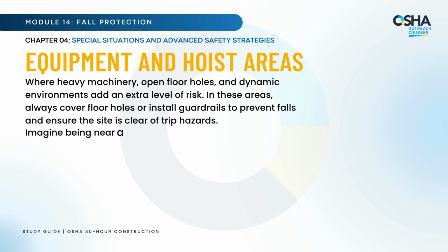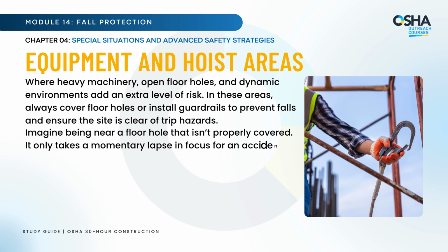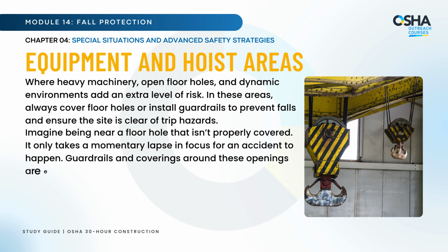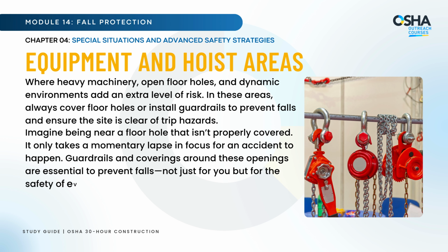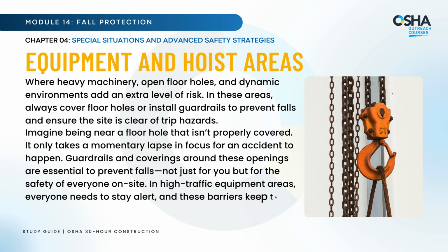Imagine being near a floor hole that isn't properly covered. It only takes a momentary lapse in focus for an accident to happen. Guardrails and coverings around these openings are essential to prevent falls, not just for you but for the safety of everyone on site. In high-traffic equipment areas, everyone needs to stay alert, and these barriers keep the site safe, no matter how busy the environment.